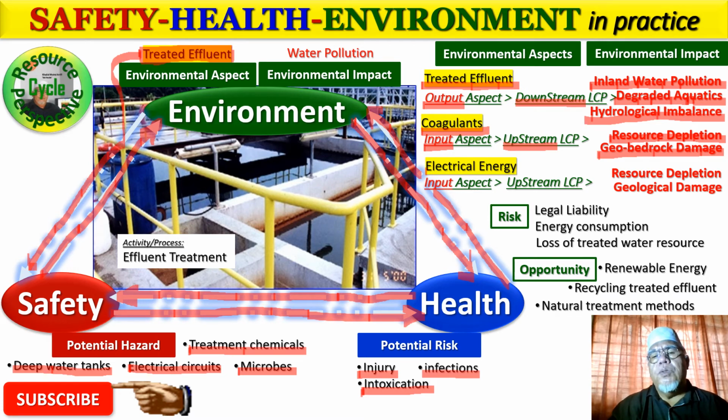Nonetheless, this industrial effluent treatment system, rather, is heavy on energy. All the pumps are electrically operated. If you have a diffuser blower for your huge aeration tank, these are power-hungry devices, and it has got to pump air through nozzles to diffuse. The smaller the nozzle, the better for the aeration tank, because of a better surface area to volume ratio for the mixing of dissolved oxygen in the aeration tank.